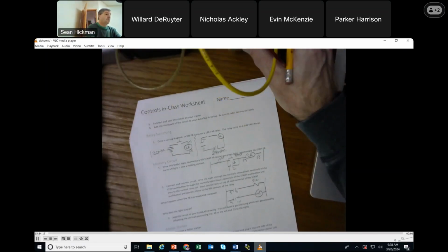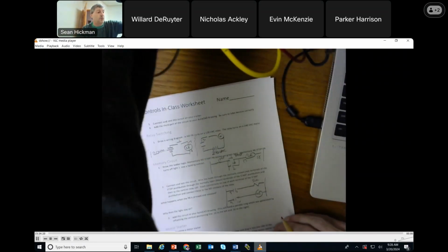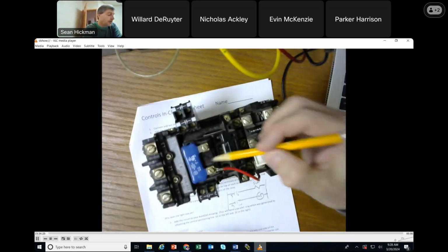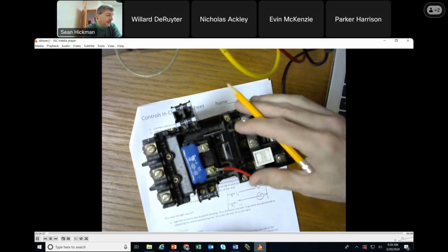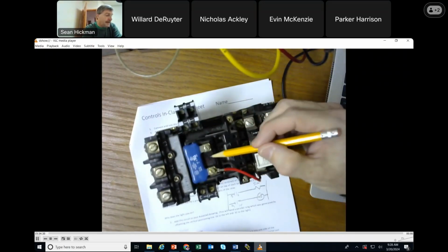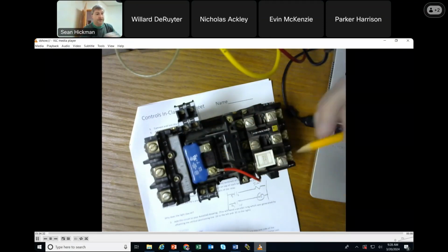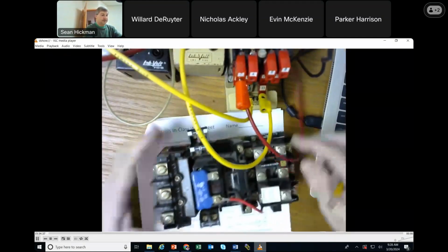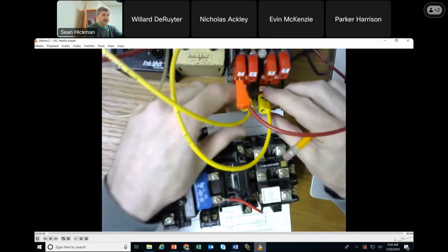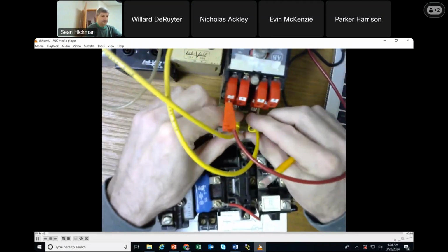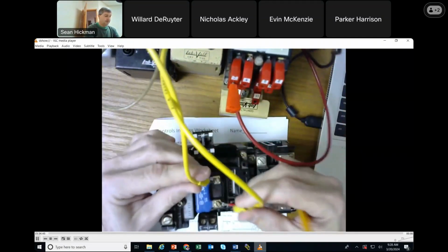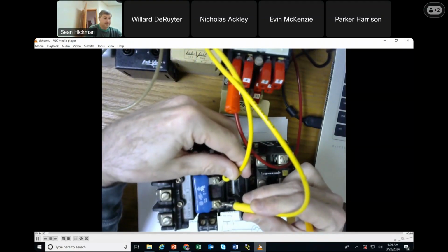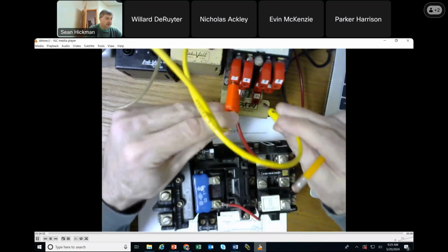And that's what you'll be drawing. So a motor starter is right here. Up here it says 120 VA, so you can't see that, but that is the coil. So if I were to take 17 and 18 right here off of here and put it onto here, well then this would come on, because this motor starter is just a relay.